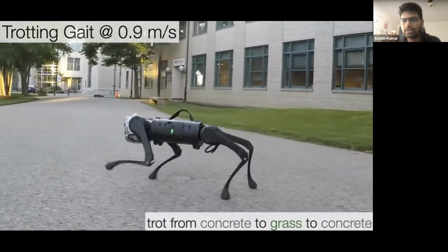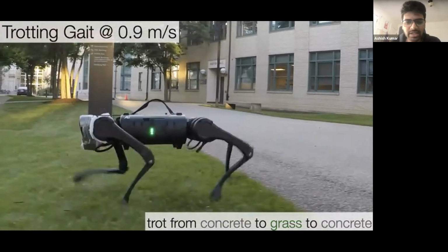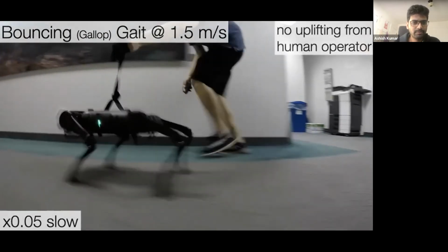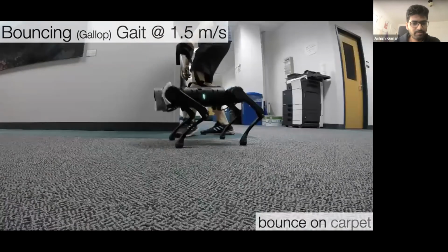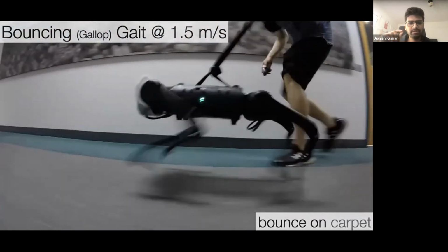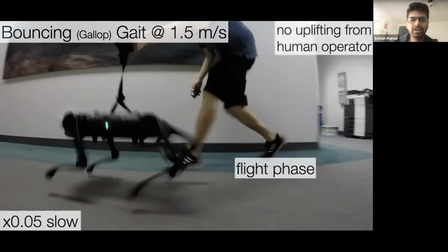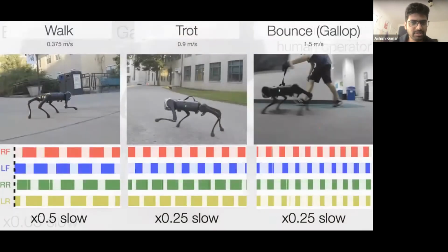So note that our algorithm doesn't know about these gaits. It's just making predictions at 100 Hertz to walk efficiently at each of these speeds. And at even higher speed, we can take it to an even higher speed, and we see that it gets to this bounce gait, which has a small flight phase. And let me play this in slower motion so that the flight phase is visible. The flight phase is when all 4 feet are off the ground, and we see that our algorithm converges to this flight phase for efficiency at high speeds.